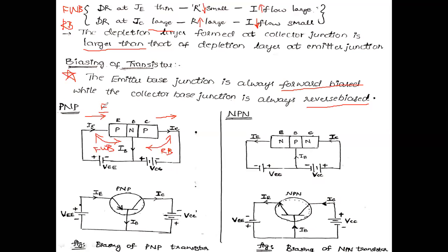This is the majority current, simply put. The emitter current, the majority charge carrier current, flows along the direction of base towards the collector. That means from emitter to base, a small amount of current goes to the base. The base terminal acts as a medium, and the flow of current is actually going to the collector only.